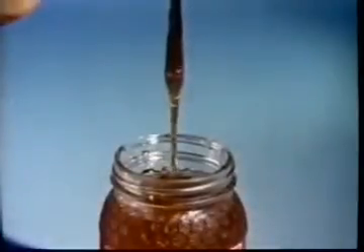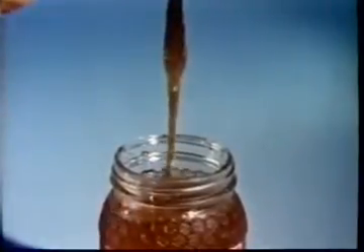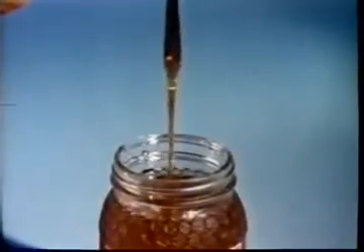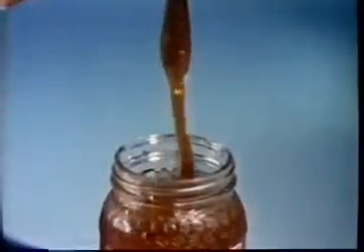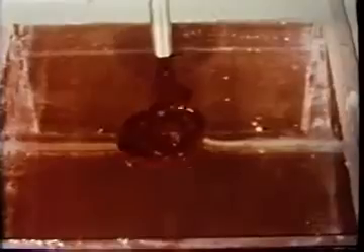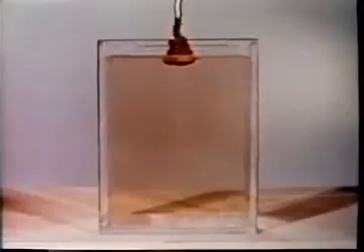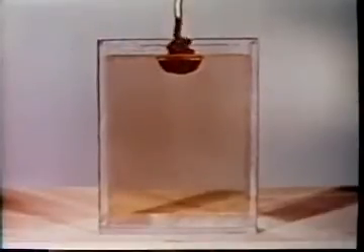Though this honey stream shows us something about the properties of viscosity, it doesn't give us any physical insight into the relative importance of viscosity and inertia. A similar set of experiments done with a controlled jet entering a quiescent mass of the same fluid can give us such an insight. In defining Reynolds number, the appropriate length and velocity to be used are the diameter and the velocity of the jet as it enters the fluid.